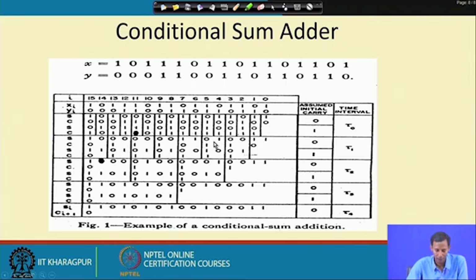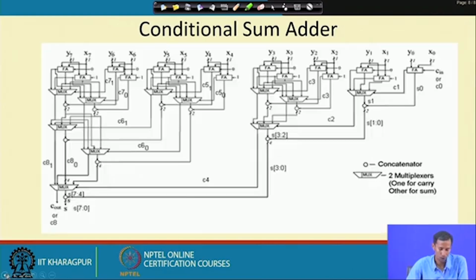So, now this again will affect what? This 1 and 1 will affect the 6 and 7 position. So, again something in this manner we have to find out, that means this x6 and s6, sorry, s6 and y6, they will affect this y7 and x7. Then again from this multiplexer we will get a 2 bit group. 2 bit group means one from this particular sum and one from the sum of this particular stage.